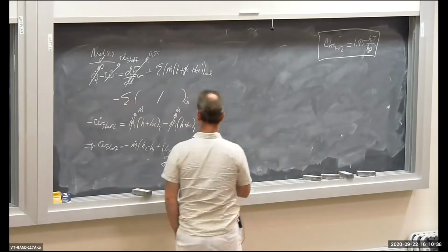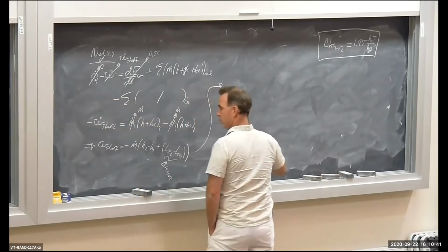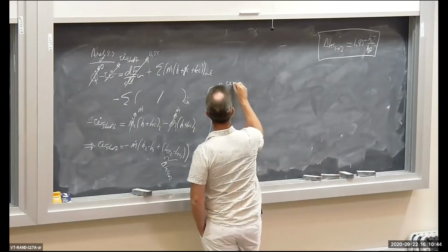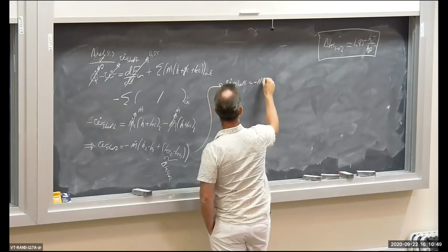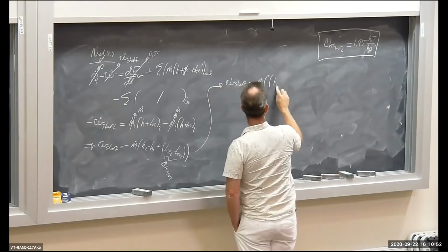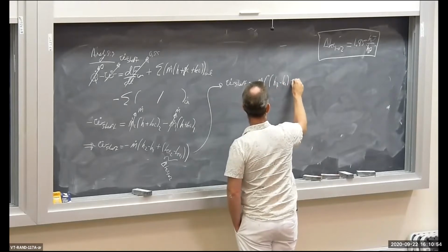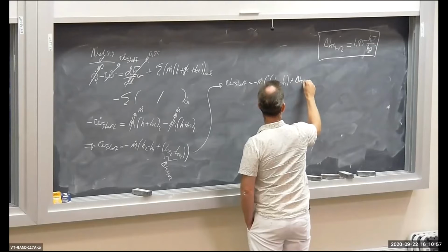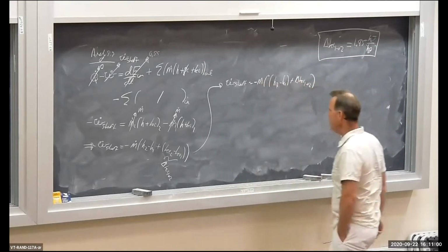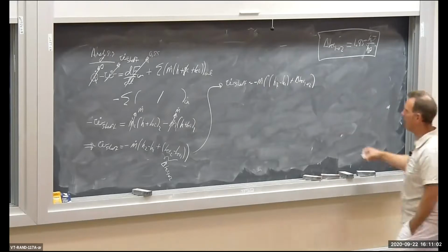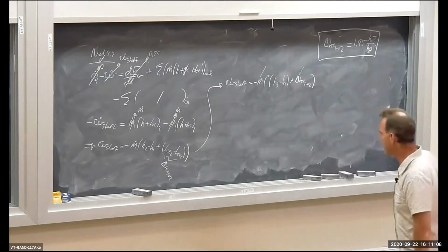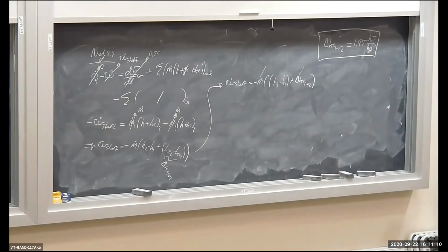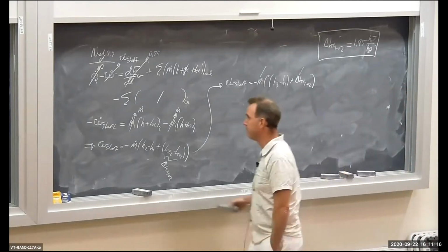So let's write out the final version. W dot shaft is equal to minus m dot times H2 minus H1 plus delta KE from 1 to 2, okay? We've already got this. By the way, we have the mass flow too. Now we need to find the specific enthalpies at the inlet and the outlet.